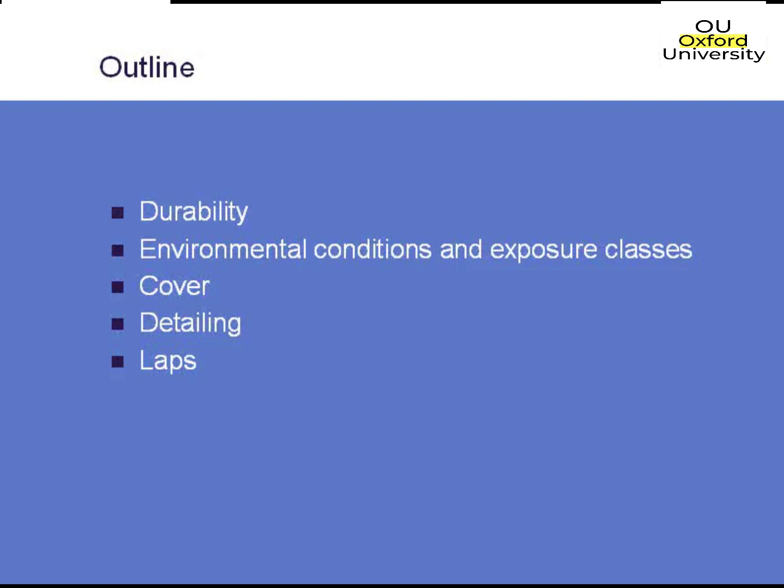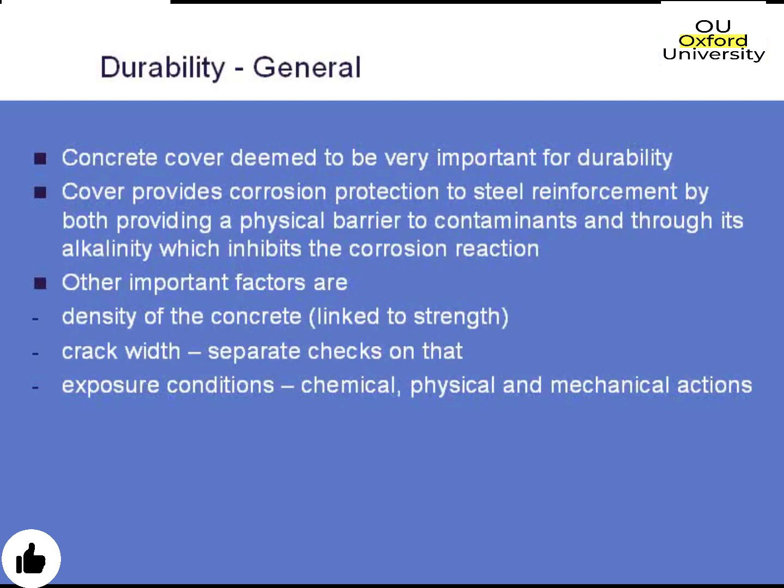So starting off with durability. Basically, in the Eurocodes, the thickness of the cover is the most important consideration for the durability requirement. Crack width in itself doesn't actually affect durability that much, and that's one of the reasons why the covers have increased a lot over the last few years. You just get better durability from big covers than you do from calculating crack widths out.